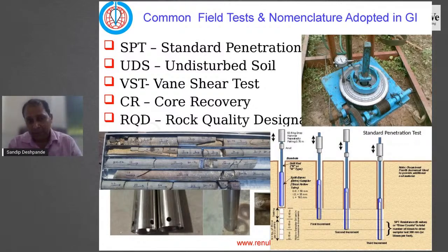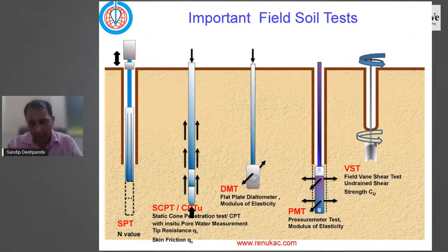And lastly lies the vane shear test, mainly to understand the low values of parameters in ground engineering studies. Coming to the rock formations, these give us an idea about the core recovery, RQD, and all the aspects of the rock stratification, which are quite significantly important, specifically when you're looking at deep-seated end-bearing pile foundations.